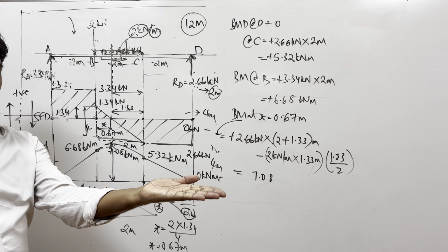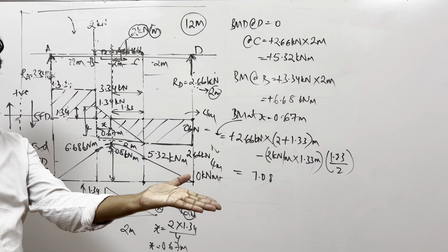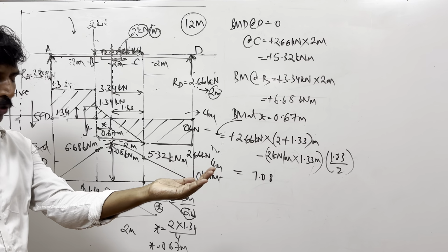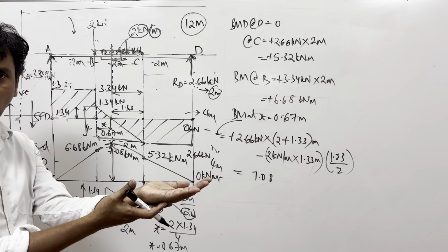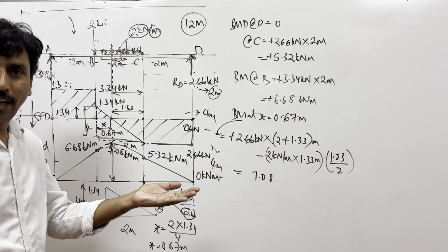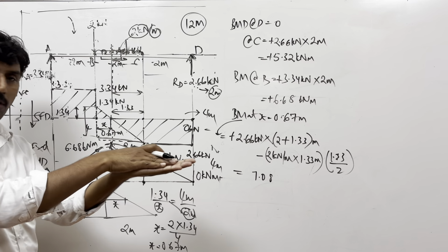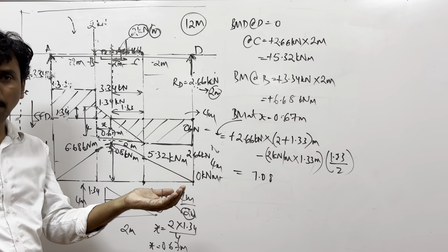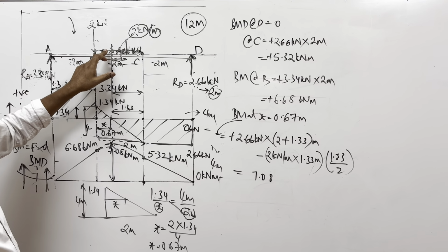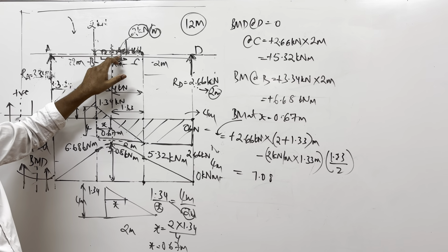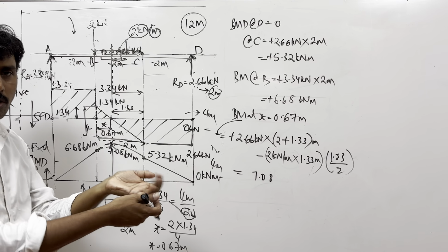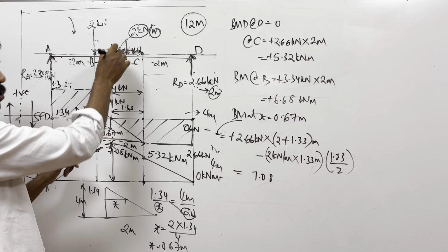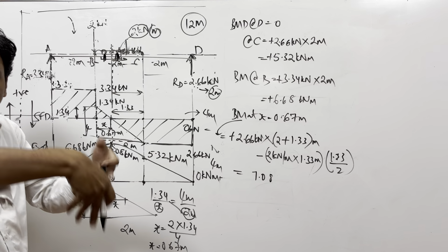Because now it sags, no? If you want to prevent sagging, suppose if I attach a tape here, if I want to do like this, so can I do this? I can't do that because that tape doesn't want to expand. If you put something at the top, now the tape will easily get crumpled. So usually when you have sheets, the sheets may actually get crumpled here, but when you attach sheet below, the sheet wants to expand, or if you put a rivet like this, rivets or welded joints or bolted joints here, so then it will be difficult for it to sag.